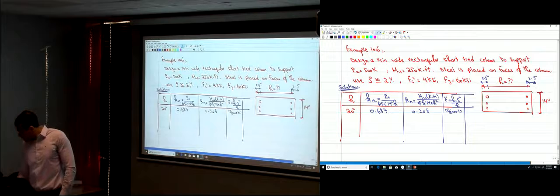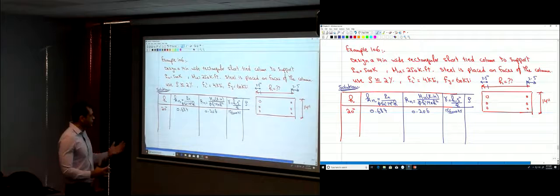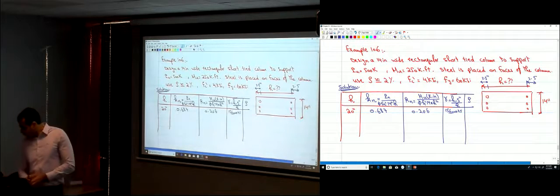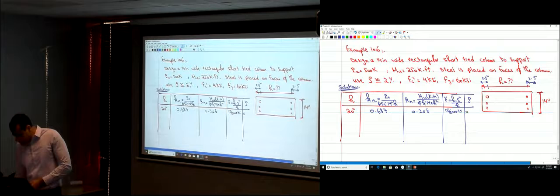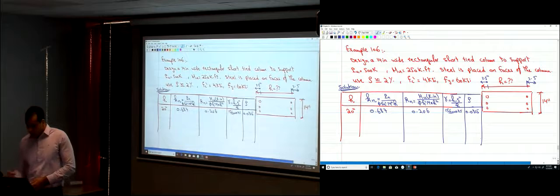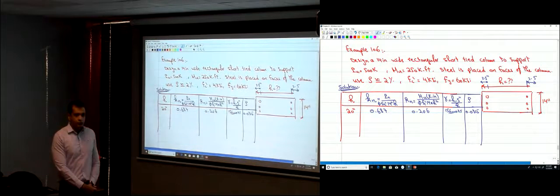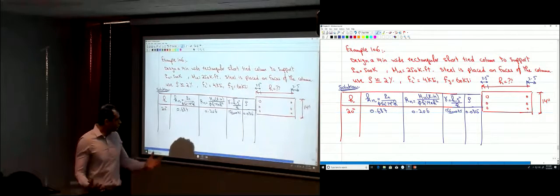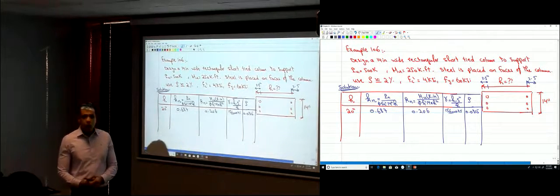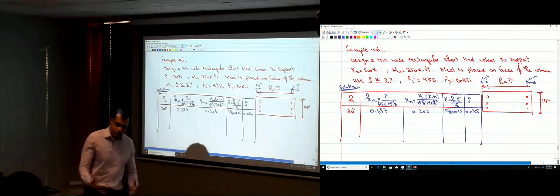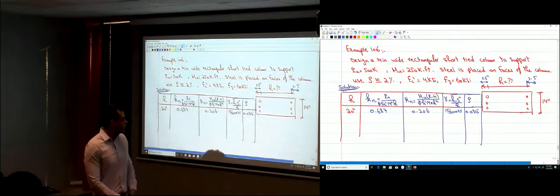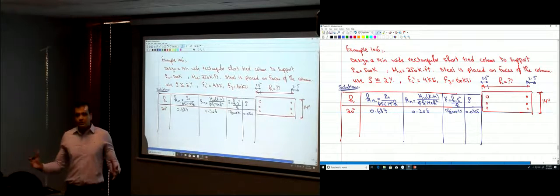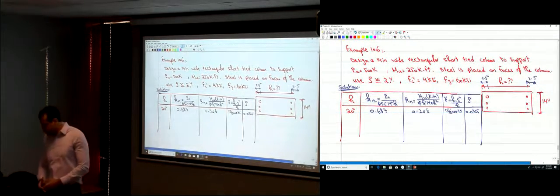So that's gamma, so I can go ahead and find rho. Rho is going to be interpolated for 0.7 and 0.8. Doing this, rho is 0.0315. Is that the rho that we're looking for? We wanted rho to be equal to 2%. We had 3%. So what would you do to decrease rho? Increase h. Increase h, okay? Make the dimensions larger, so rho becomes less, okay?